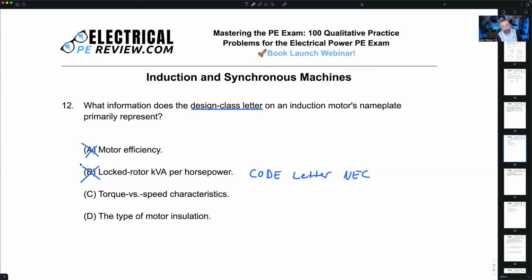I can't believe the power factor on this thing is only 52. That's almost hard to believe. I'm used to medium voltage motors or low voltage at 480. For me, a small motor is at least 25 horse or 50 horse. Even those are going to be at least around 80% power factor and mid 80s or 90s efficiency. So it's not the efficiency.